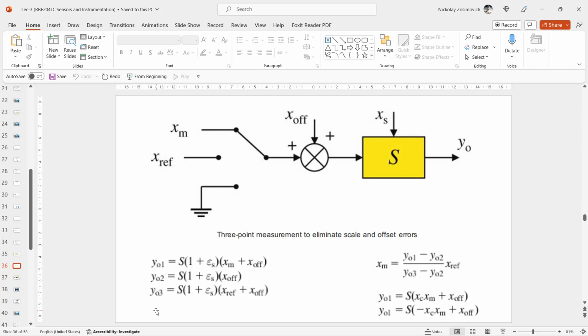So flipping is performed either by changing the carrier signal in a modulating sensor or by rotation of the sensor itself. An example of a modulating sensor is the Hall sensor for the measurement of magnetic field strength. This is a modulating type sensor because the output is proportional to both the input signal and an auxiliary signal, in this case, a DC bias current.